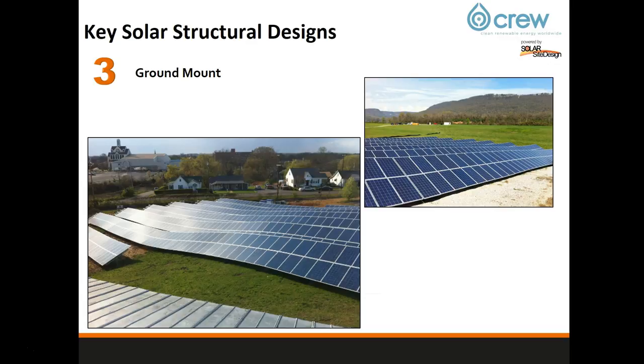Okay, team, now we're getting into the big projects. These are ground mounts. Does the commercial or industrial property have land available around it? If so, let's look at ground mounts. These are great projects. Why do we like ground mounts? For one, we can optimize the ground mounts to the tilt and azimuth, so we can get the maximum potential, the max placement of that system.